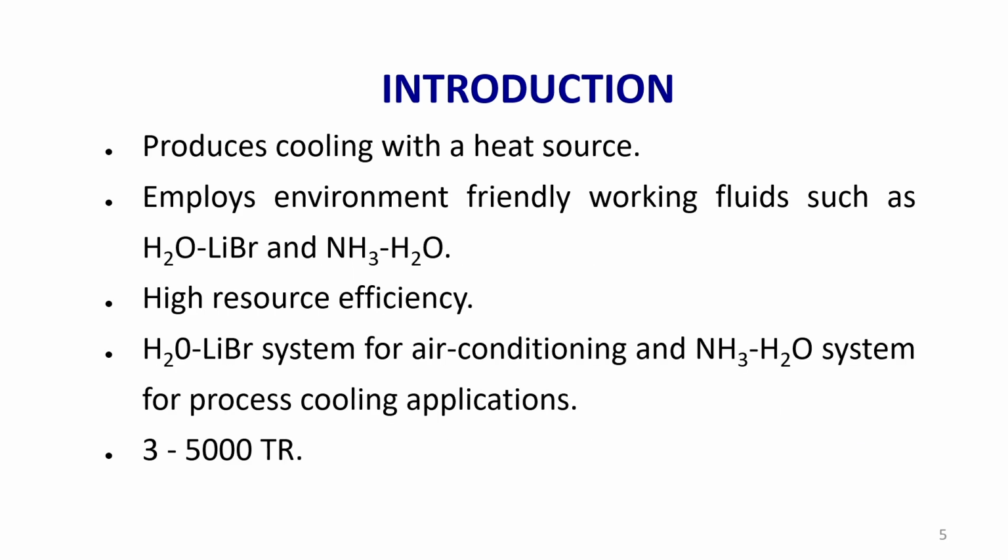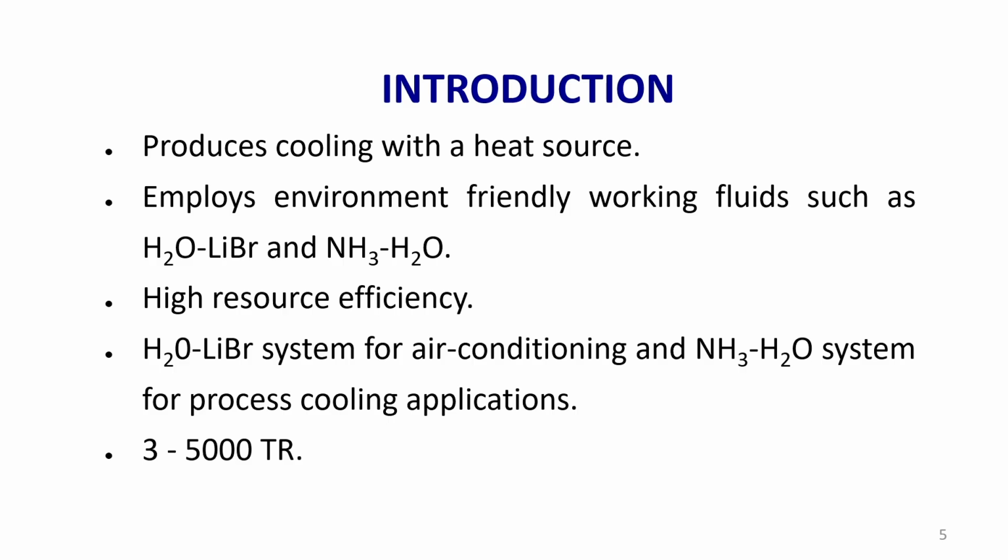The alternative is the vapor absorption system, which does not use a compressor. It is also a refrigeration system or an air conditioning system which produces cooling with a heat source. So, this is very important. It produces cooling with a heat source. That doesn't mean that it does not require electrical energy at all. It requires a very little amount of electrical energy to operate a pump. The pump is called a solution pump, which I will explain in the working principle of the system in the next slide, in the subsequent slide.